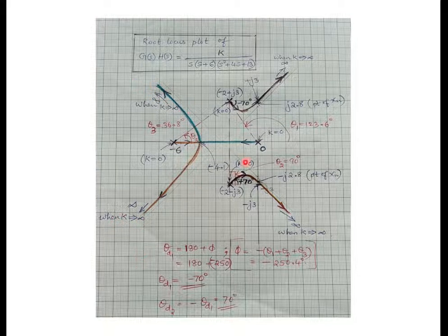Okay, this is coming like this, that is, two root locus branches reaching the point minus 4.1 and breaking away. And then you have to find the complex pole angle of departure. So the root locus branch starts at this complex pole, but the angle of departure of the complex pole you have to find, not like on the real axis, where it will always be at 180 degrees. But here, how will you find it?